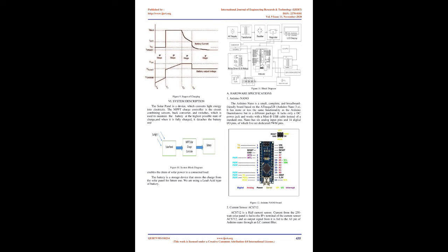The best way of preventing thermal runaway is through the use of a temperature-compensated battery charger. A temperature-compensated charger adjusts the float voltage based upon battery temperature. Temperature-compensated chargers will increase the reliability and prolong the life of the battery/charger system. They are especially useful for batteries located in areas where temperatures may be significantly above ambient conditions.